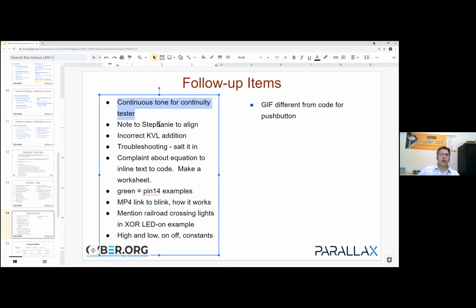But it might also mess with the circuit. And so another thing I have to do is look at what happens when you turn the speaker on and off. Is there a diode inside the microbit that protects the circuit, or would I be inadvertently modifying the circuit with the probe? If that's the case, the decision has to be between updating our documentation so that all the continuity testing happens on P1 and P2 instead of P0 and P2. Those pins will be really close.